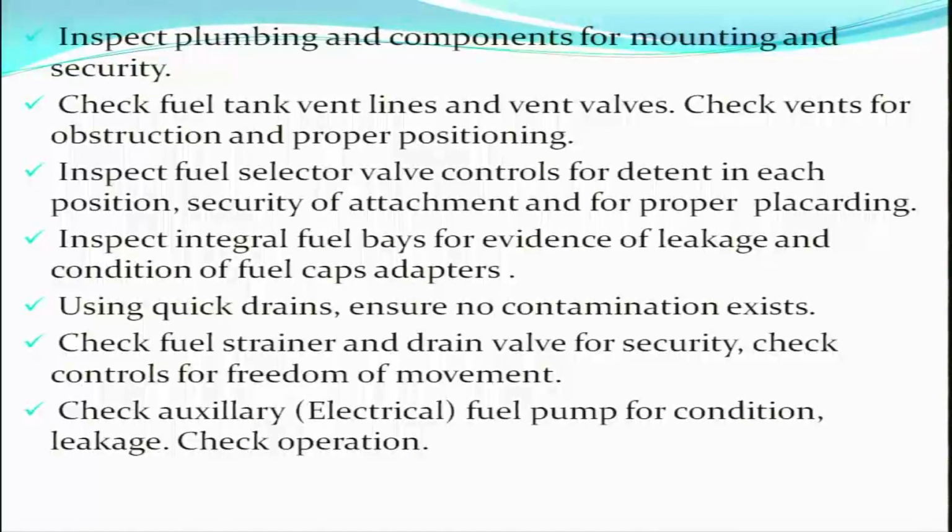Inspect integral fuel bays for evidence of leakage and condition of fuel cap adapters. So we need to check that the fuel bays are free of leaks, the fuel caps are firmly placed and the cap adapters are in proper condition. Using quick drains ensure no contamination exists. So we need to check the drain points, we need to ensure that there is no contamination in the drains.